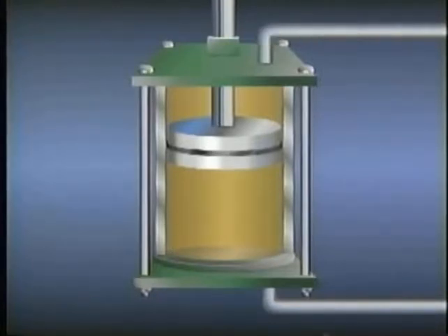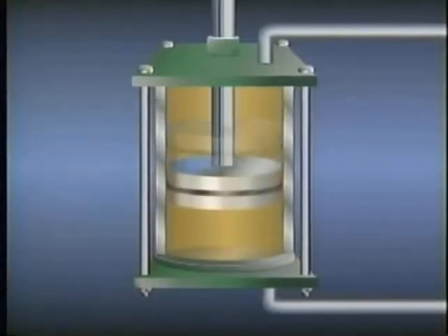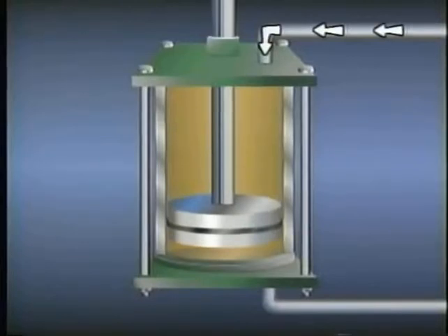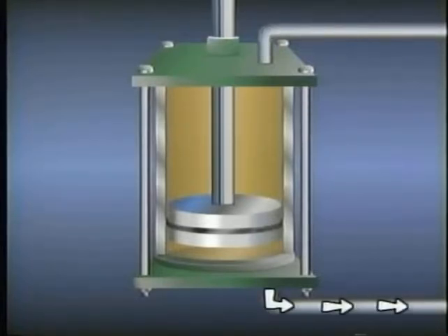The piston stops when the flow of fluid through the lower port is stopped. Fluid is then trapped on both sides of the piston, effectively locking it in place. To return the piston, fluid is supplied through the upper port, causing the piston and piston rod to move in the opposite direction. When this happens, an equal volume of fluid flows out of the lower port. The flow of fluid entering the cylinder and bled from the cylinder is controlled by a directional control valve.